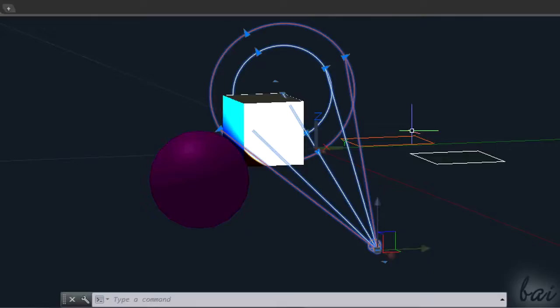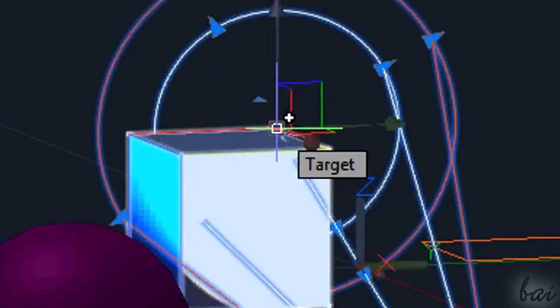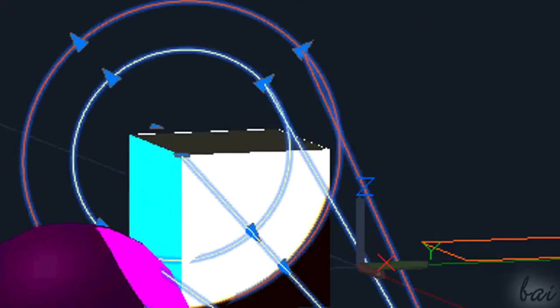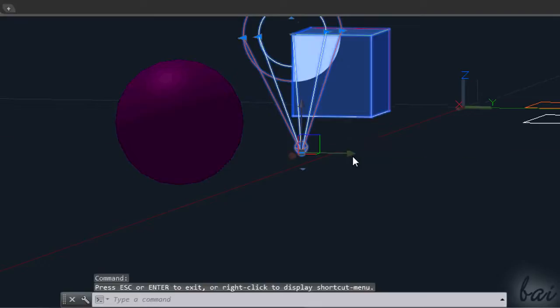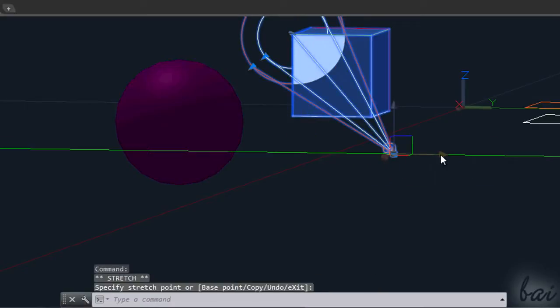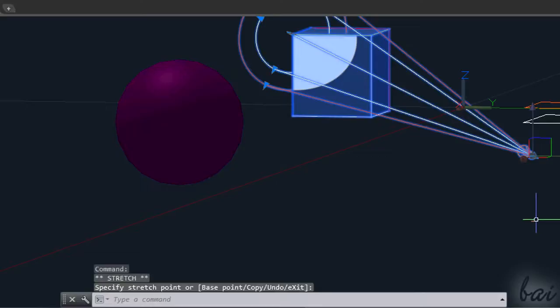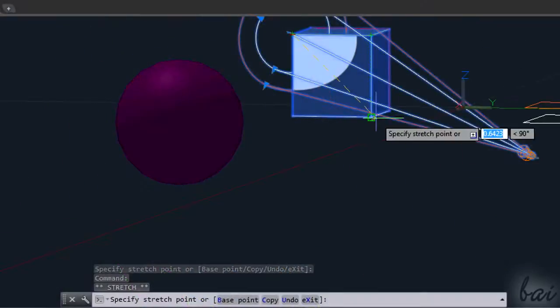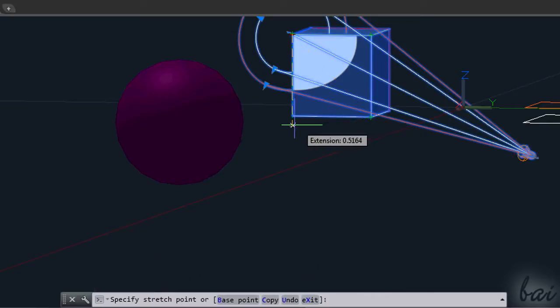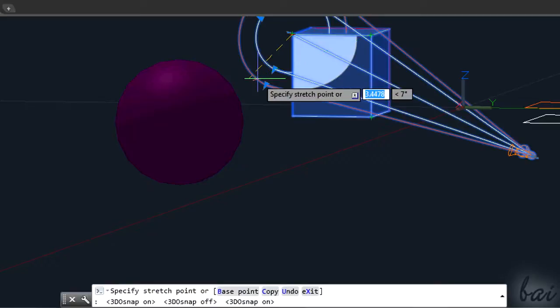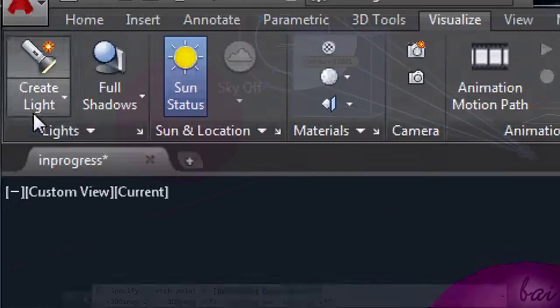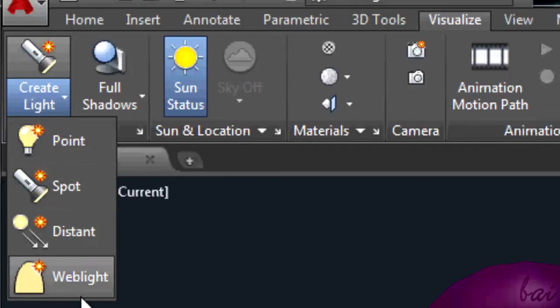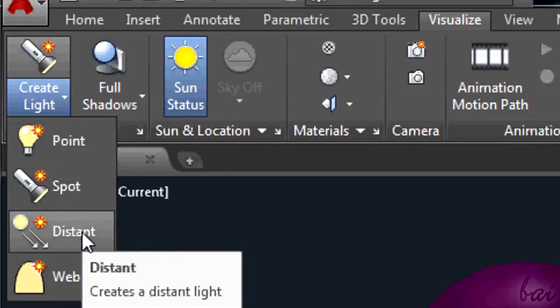This kind of light has a target, indicated by a blue square on the center of the virtual circles. Whenever you move, the spotlight will always be directed towards the target. Just drag it to change direction. If you need to snap two objects, just press F4 key to enable or disable snappings. You have other sources available. Check them if you are interested.